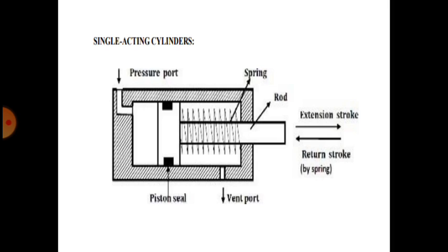The cylinder barrel is machined to a high surface finish so as to form a close fitting with the piston. The piston is fitted with rubber seals or metal rings to make the mating leak proof. The piston rod attached to the piston is supported with bearings at the rod end of the cylinder, as shown in the figure. A seal in the rod helps in reducing any leakages from the cylinder.